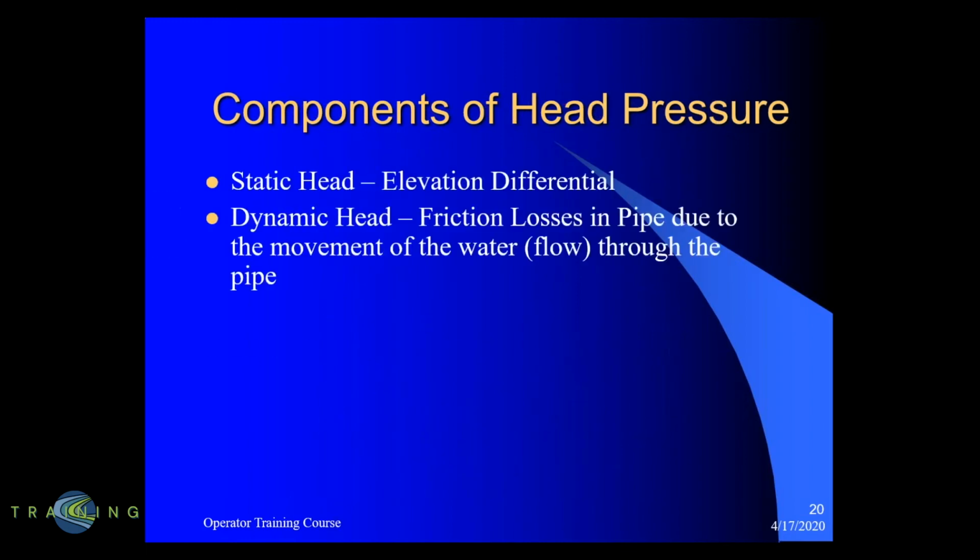Now we'll talk about the second component of the duty point, which is head pressure. Head comes in multiple pieces. The first thing that we consider is our static head, which is our elevation differential. We're always looking to find out what the elevation is at the pump and what the elevation is at the highest home that we're pumping to, or in sewage, maybe pumping into a manhole at a distant site. But that's the first part of head.